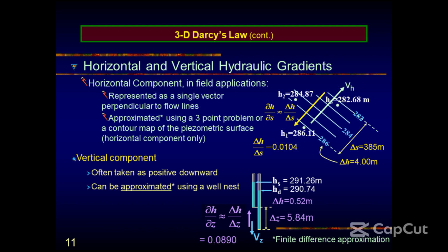Let's say this is the water table. So if you take lateral segments, some width across, it will be points of equal head, because this way it is decreasing, but laterally, perpendicular to this, it will have equal head, isn't it? Are you following? All right.